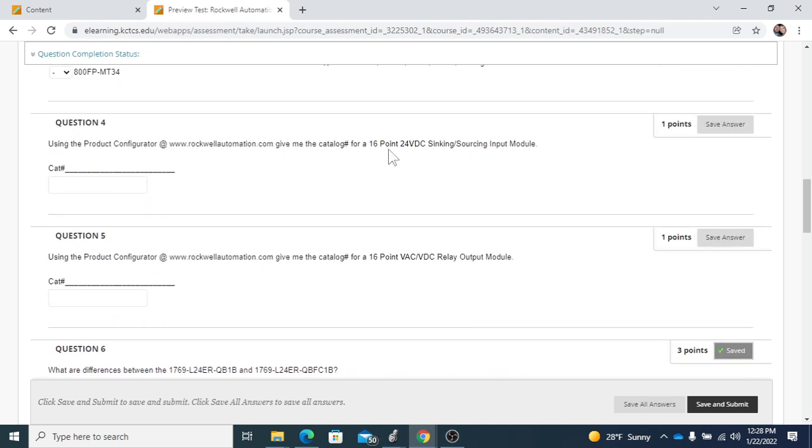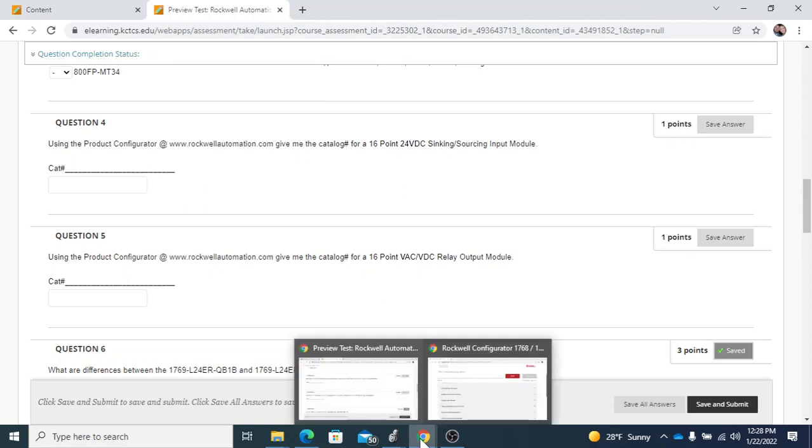This right here, I'll just let you know, is going to be a digital I/O card. This is also going to be a digital output card. So what that means is that this input card is either going to be on or off. The inputs are on or off, digital, discrete. The relay outputs are also the same. They're either going to be on or off. So these cards are not analog. That should be a good pointer for you to make sure you get this correct.